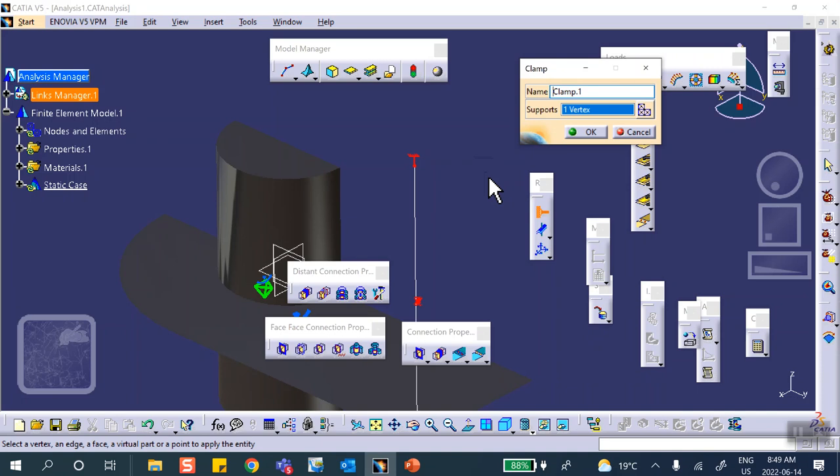It has to be a vertex, okay? But I don't have it because I didn't create it like that. I said point and direction. There's nothing up there. But somebody could have done point to point, created 2 points, and then connected them with a line. Then make sure when you do that, you hide that point up there, because if you put it on the point, you'll take it. But you won't see it later on when you run it.